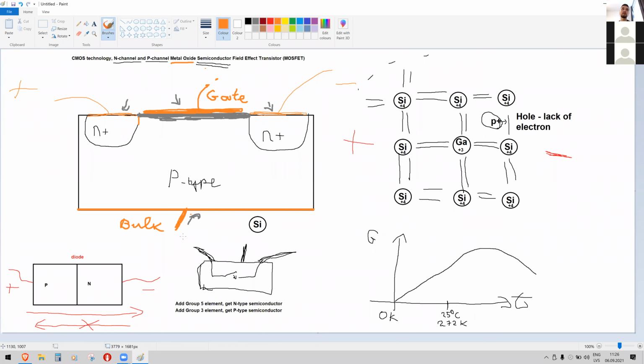And one more thing, bulk is always connected to one of the pockets like this, because it's just easier to construct schematics with this type of connection. As a result, the transistor actually has only 3 wires because the 4th wire is internally connected to one of these 3 wires.